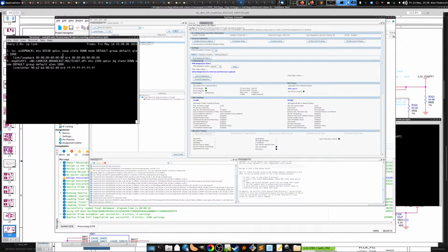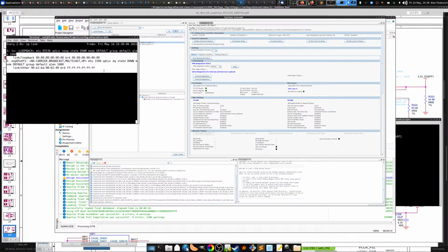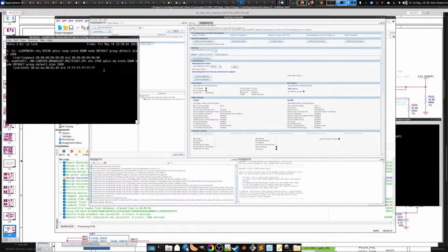One thing that happens with some Ethernet MACs and/or PHYs is that they will forward some link status information. So if the RX link isn't working, then it will report local fault on the transmit side. What I think is happening is that since the receive side on the board doesn't seem to have figured itself out, it's reporting a local fault, and then the NIC is reporting that the link is down. I guess it makes sense, but it would be nice if it would differentiate between local fault versus nothing.